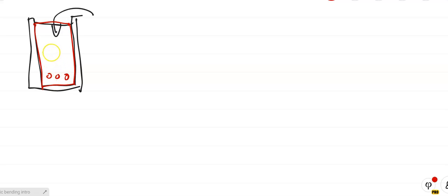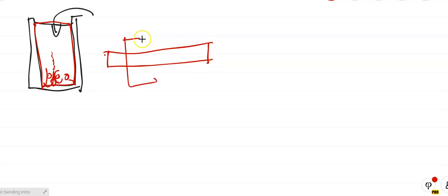Okay, why? So that the concrete can go down between the bars, sit on the formwork, so that when the formwork is taken away, the concrete is sitting as a rectangle, all around the bars and sitting in the corners there. And of course, if that's my beam over there, let's say it's finished pouring, and I take a cut through it like that and look at it, it'll be a rectangular section with the bars there, made up of sand, stone, cement, and water which is not drying.